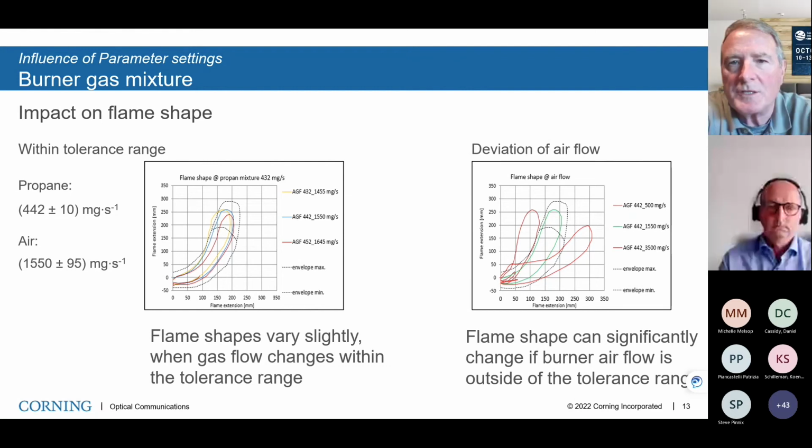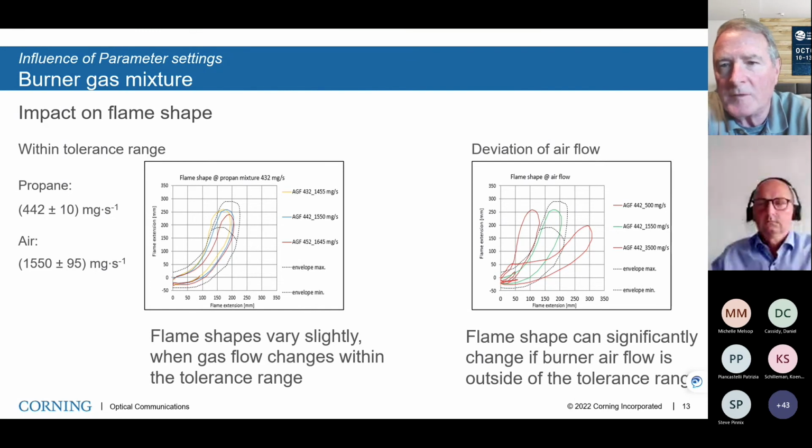Two more questions. Inconsistent flame shape can impact the results, obviously. We've talked about that. Do you burn a wooden grid as a rough verification of the flame envelope, or do you just verify through the gas and air supply using a flow meter?